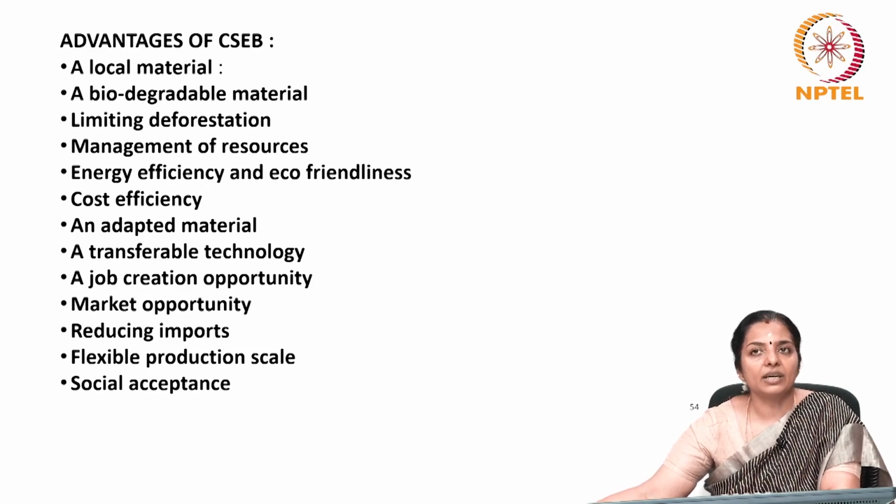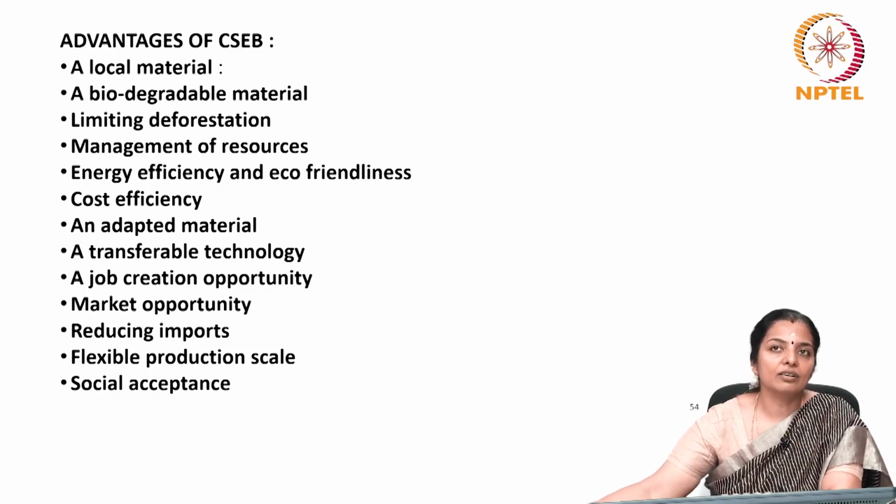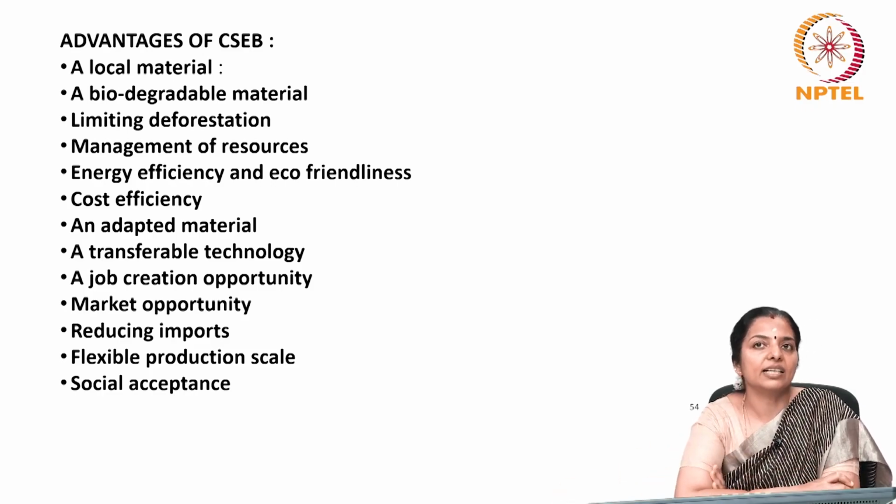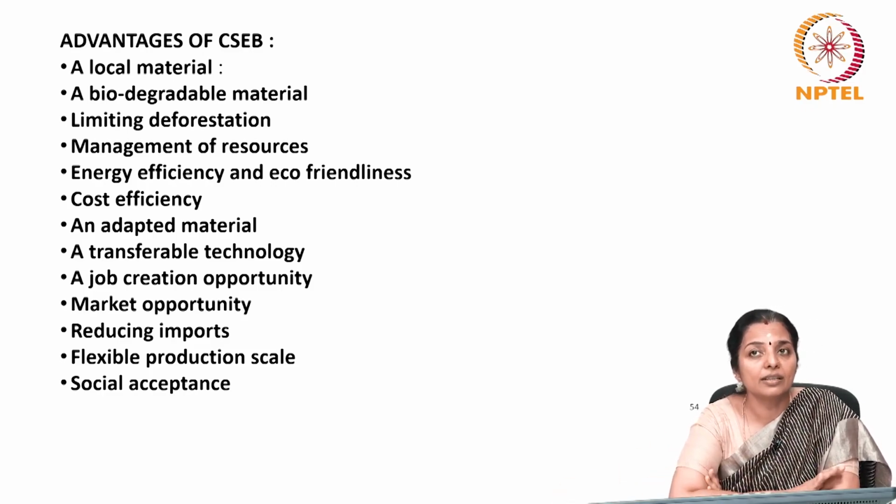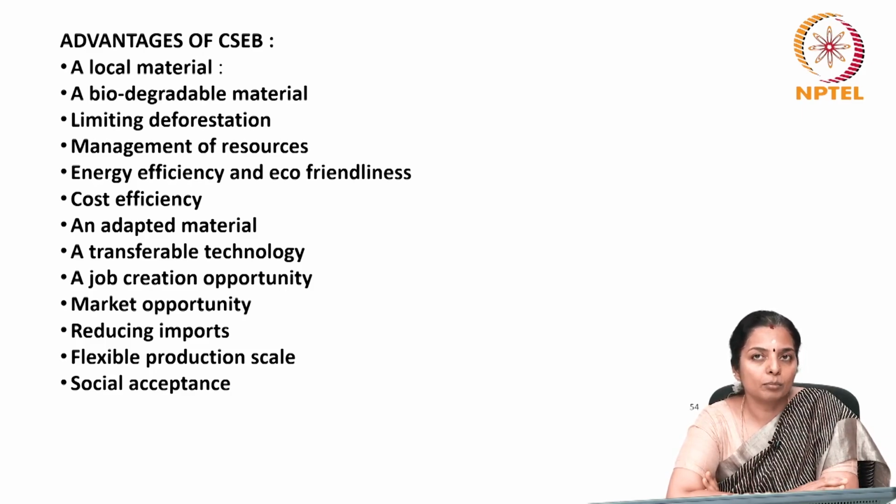But let's imagine a building fallen down and a jungle grows on it. The biochemicals contained in the humus of the topsoil will destroy the soil cement mix in 10 to 20 years, and CSEB will come back again to be again made into cement blocks. There is very little deforestation because you don't need anything to fire these blocks. So this will save us a lot of timber and forest which are being depleted very quickly.